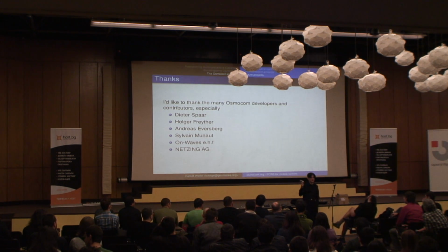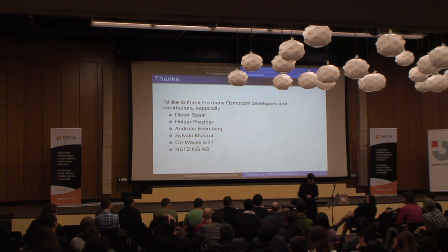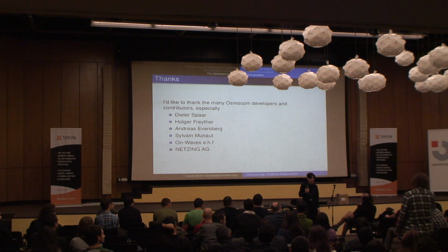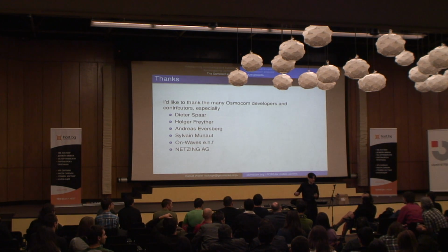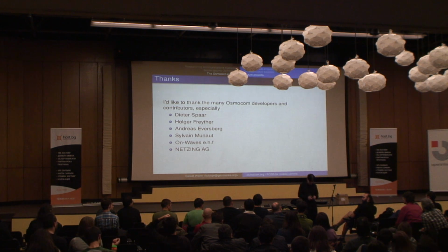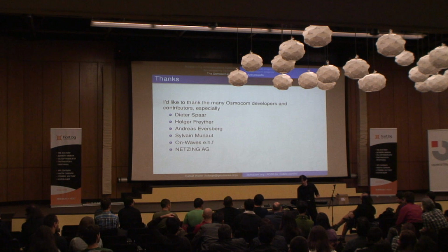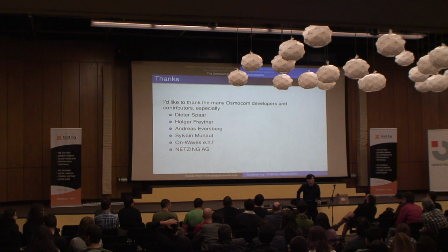So for these phones here, for example, what we do right now is we connect them to a PC. And most of the software we run on the PC, and only the lowest layer 1 implementation we run on the phone. It's not that we couldn't run everything on the phone, it's just that it was easier to develop this way. But what would be fun is if we could actually run all that software inside the phone, and we can cross-compile everything for ARM, and that's not a problem because there's an ARM processor inside. But then somebody would need to make one of these user interfaces, for example, for scrolling through a menu or entering a number, and so on. So this is basically ARM embedded development on a small microcontroller with little RAM and little flash. But you can use a C compiler, and you have to directly talk to the hardware. So that's not special knowledge like GSM protocols.